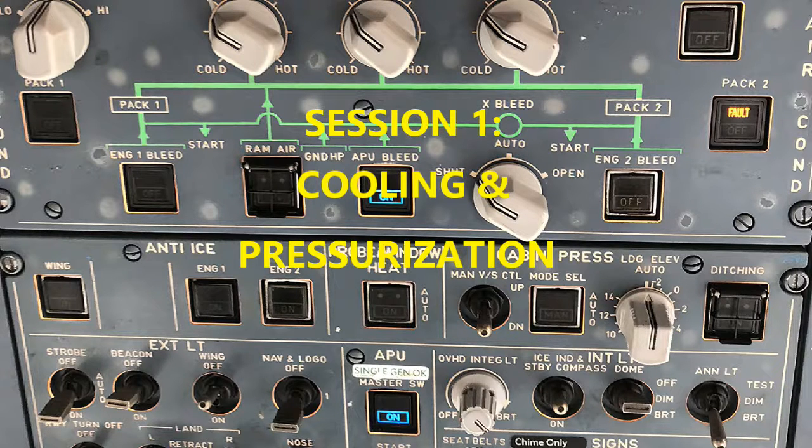We talked about temperature indications, and the other position is going to be your ram air inlet position. Okay, so here's where things change a little bit. We're going to talk about something fully in flight. A green vertical line indicates that the ram air inlet is fully open in flight. Remember I said that the pack flow control valve position with a green vertical line indicates that it's not closed. It didn't say it was not fully closed, it's not closed. But when we talk about the ram air inlet position, that green vertical line means it's fully open in flight.